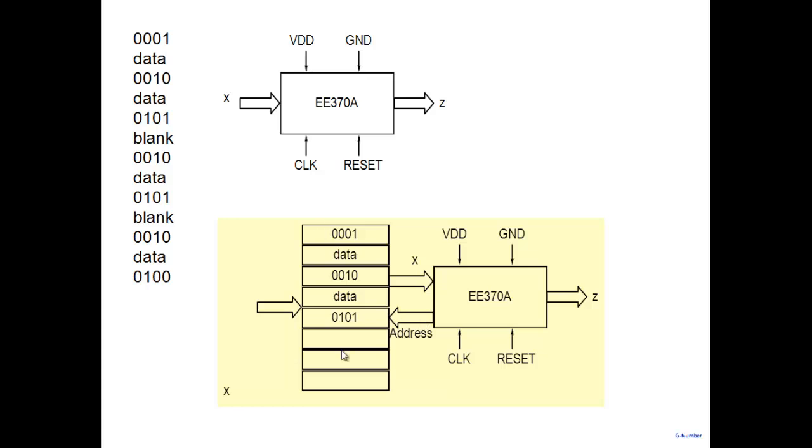Because note that it's a series of registers here. For example, if I have 16 registers here, then I need a 4-bit address to decide whether I should take the data from here or here or here or here or here. This IC should supply the address. So note that if it supplies the address here, then once the address is available here, the address is decoded and one of these things is enabled and it supplies the appropriate X here.